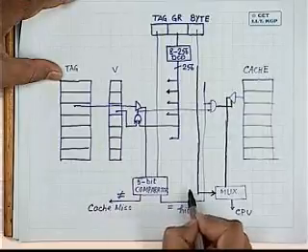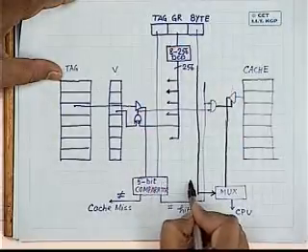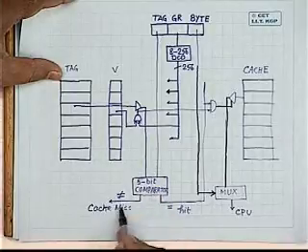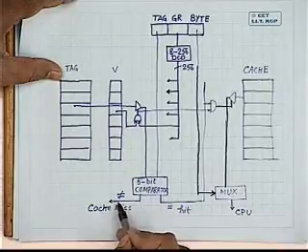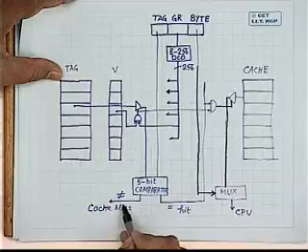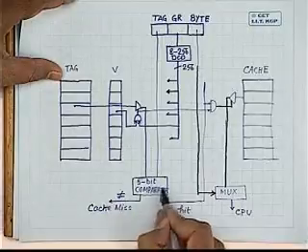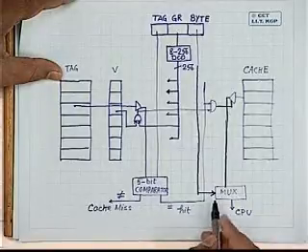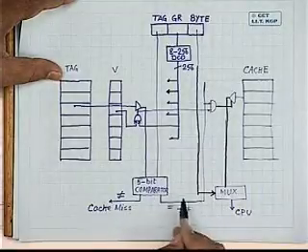They will go to two different comparators. This tag field will go to the other inputs of both the comparators. On the output side, I can have a situation that both the comparators give a condition not equal. So only when both the comparators indicate that there is a cache miss, that is a true cache miss. That means the cache miss outputs of both the comparators are to be ANDed together to indicate that there is a cache miss. Cache hit will be when one of the two comparators gives an output 1. That means the hit outputs of both the comparators are to be ORed to indicate there is a hit.